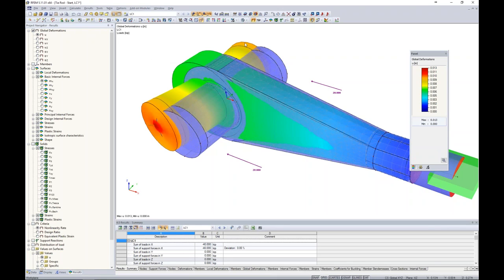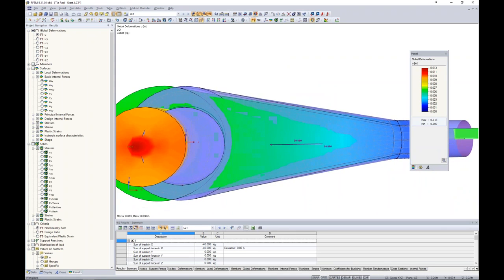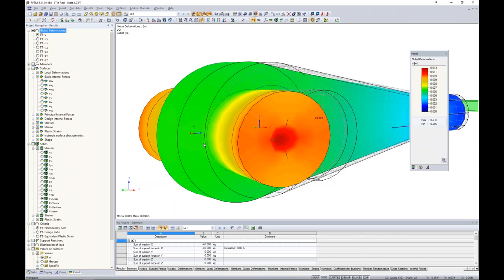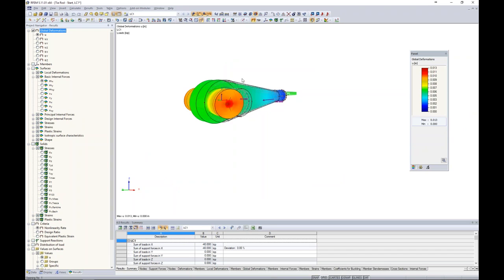So with this bolt element passing through the eye, and we turn this into elevation view and maybe into wireframe, we can see here that it looks like the bolt is fully fused to the front portion of this ring element. This is not really what's going to happen. In reality, what we would hope to happen is that this bolt would release away from the ring element where we have tension forces, but in the back, we would still have full fixity where we have compression where the bolt's bearing onto the ring.